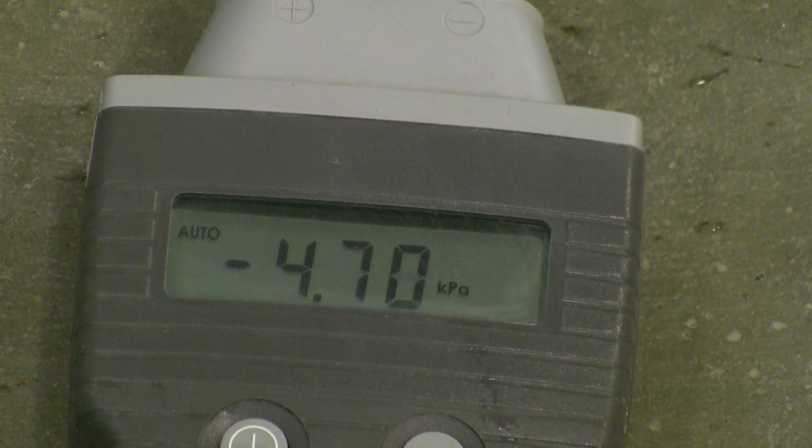I left the bench flow setting the same. All the valves are as previously, and so we will assume that the flow rate is the same as was quantified previously. So now this is the final fitting on pipe path A, gate valve, item number 21. So measure the pressure difference there.